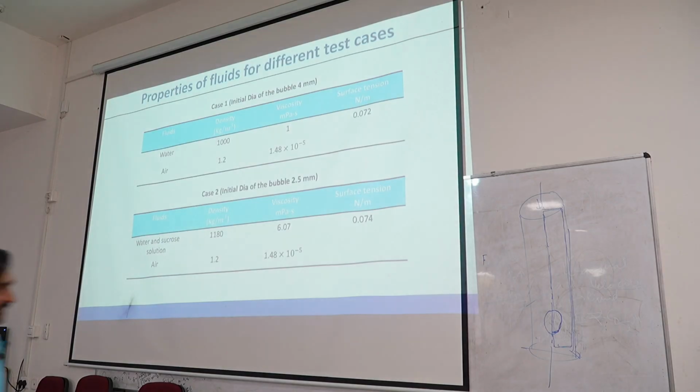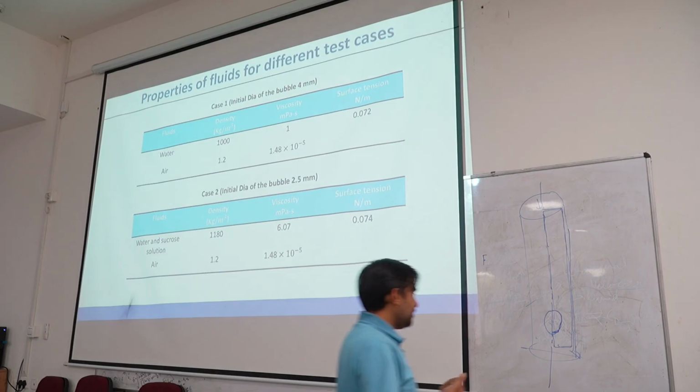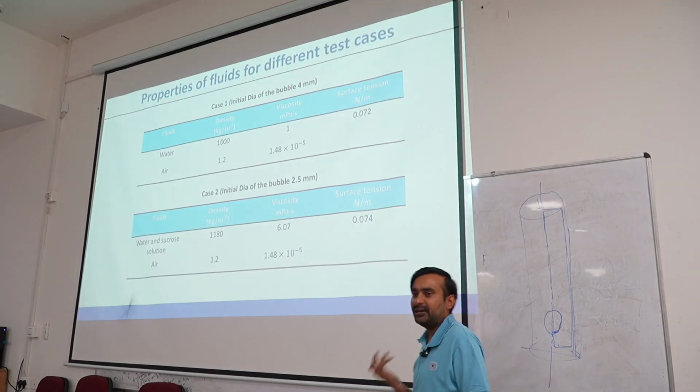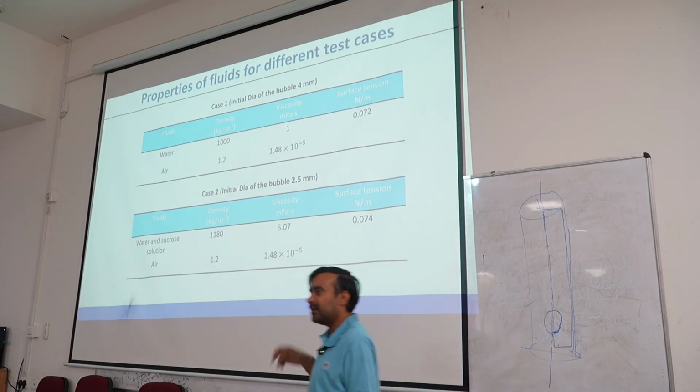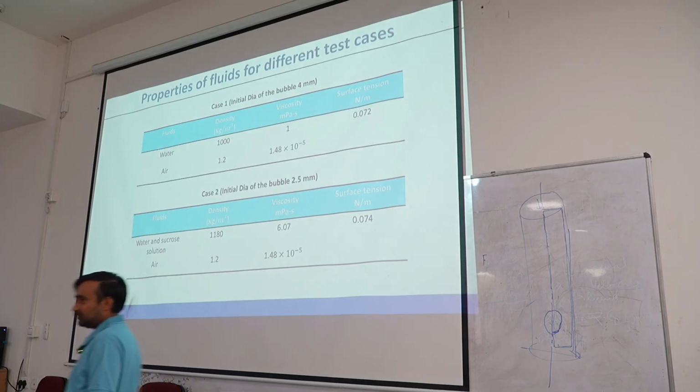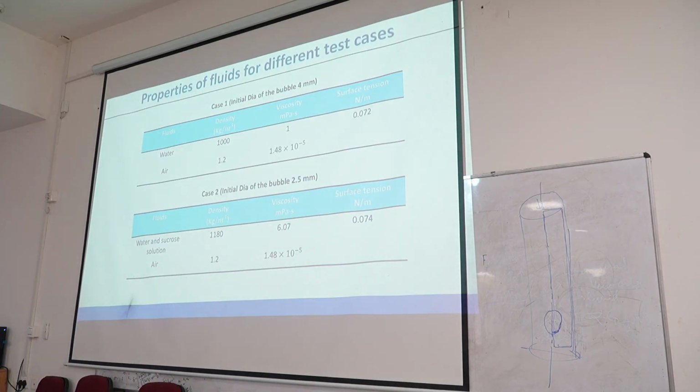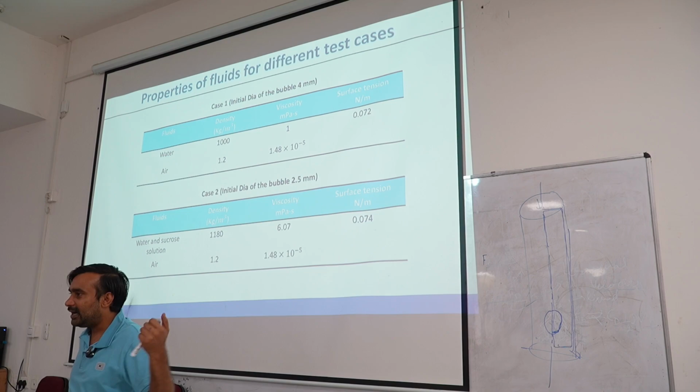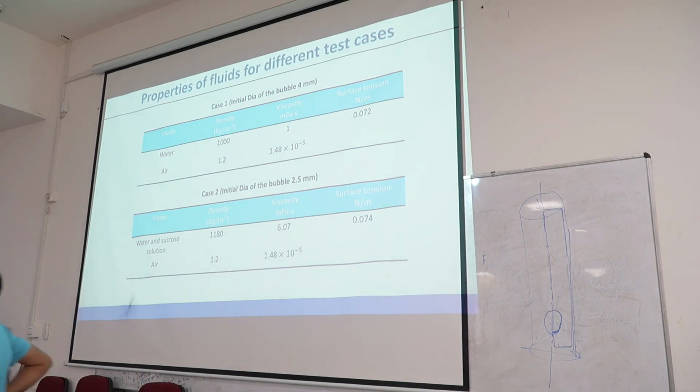Okay. So, this problem is giving me one geometrical advantage: instead of doing the complete 3-dimensional simulation, which may take a good amount of time and resources, I can simply do a rectangular case, which I can easily solve with less resources and less computational cost.